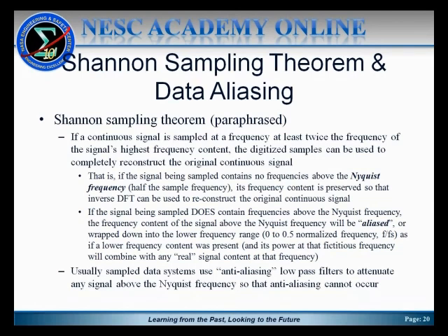In other words, for a given sample frequency in, say, your discrete controller, you'll actually apply a low-pass filter that will cut off any frequency content above the Nyquist frequency, so aliasing cannot occur because those higher frequency signals will not appear in the filtered signal you're actually processing.